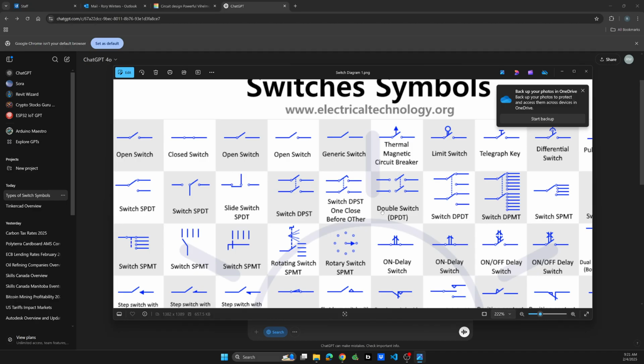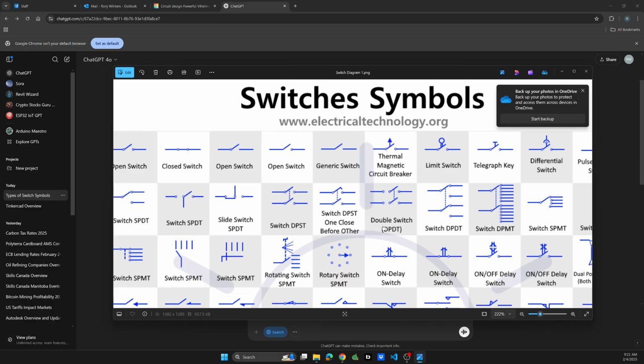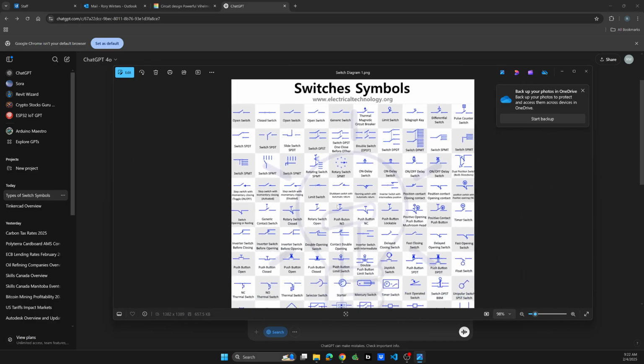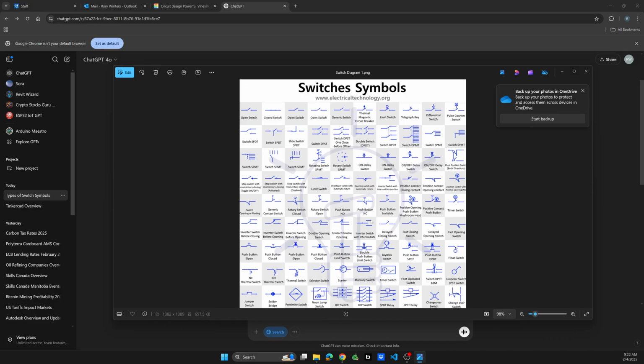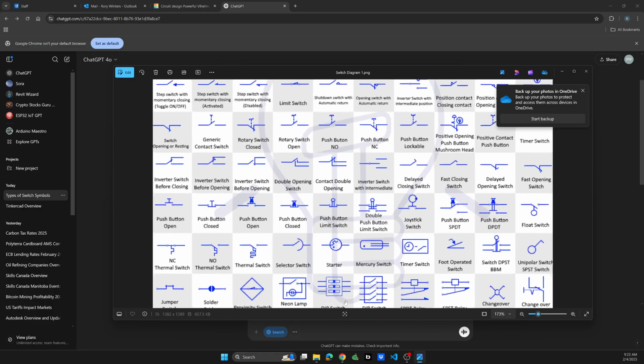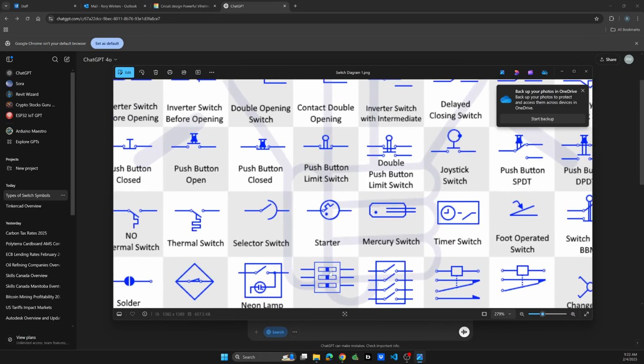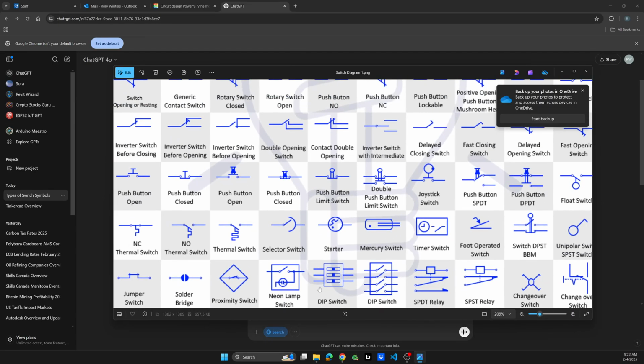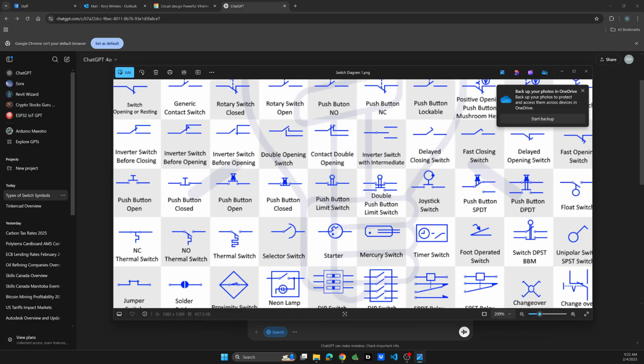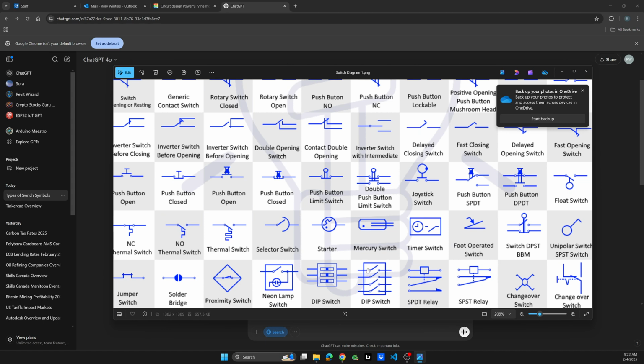Okay, so the intention here is not to exhaust the number of switches. You can see that from zooming in and zooming out. Now on the bottom here is a dip switch, and we'll see if we can get in closer on that one. The dip switch is essentially a series of single pole, single throw switches, which you can tell from this diagram here. You've got your pole and you've got your throw, and you can select them one by one and turn things on. Okay, that's enough of the theory part.